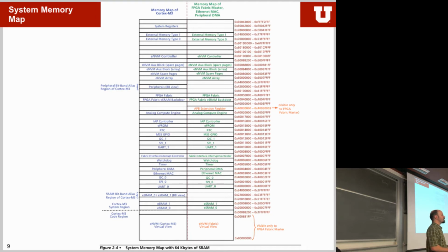What benefit would that give you over just using a mask, like an ANDed mask or an XOR mask? Sometimes you really don't want to touch other bits. Even if you AND it, or if you, for example, read something out of it, sometimes you really only want to go and read one bit and not touch any of the others. That's when you would go into this particular area. So with a mask you read it out, mask it, and then bring it back. Yes. This will be one instruction done. Correct. I rarely use it.